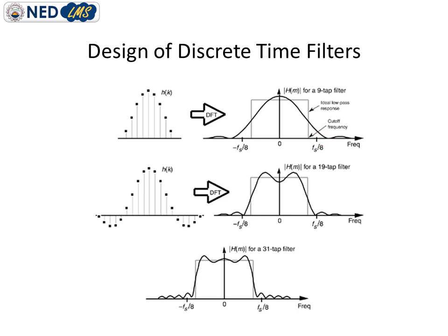However, we cannot achieve the ideal response, but we can get very close to it just by increasing the filter coefficients. As you know, the sinc function is everlasting, however it approaches 0, but as long as we take the maximum number of coefficients, we will get a very sharp response.